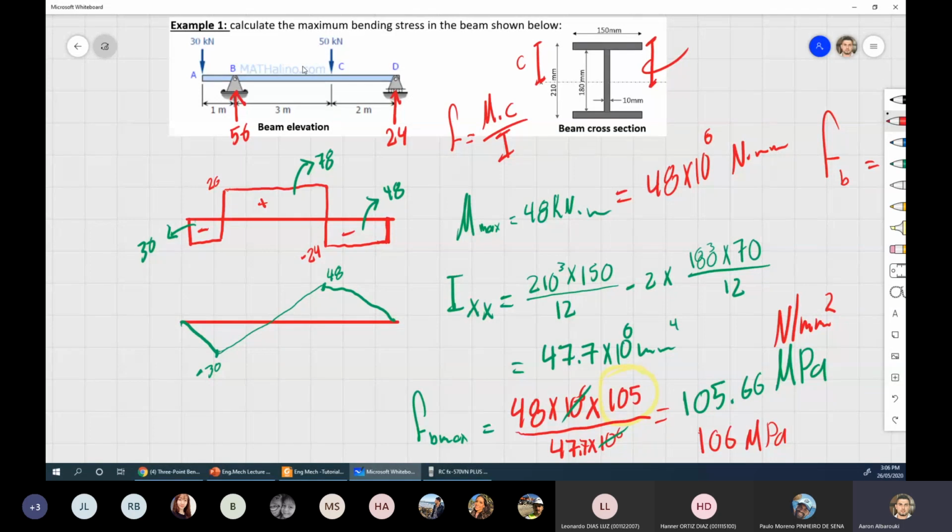What we do is use an educated guess based on experience, statistics, and education. We make our best guess to estimate this 50 kilonewton and 20 or 30 kilonewton. So those may vary. That's why we have to always keep safety factors, and not only that, but also